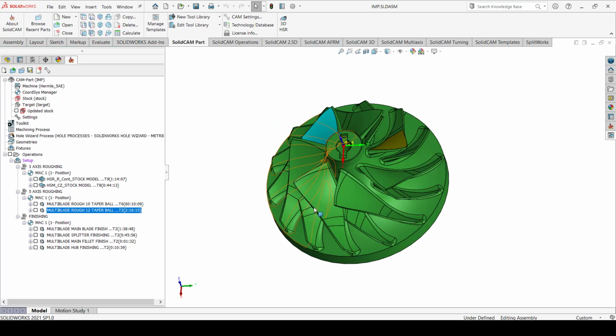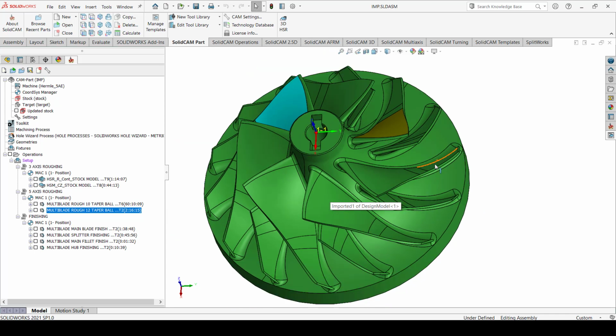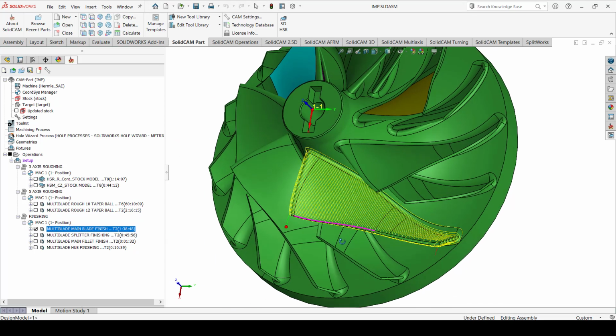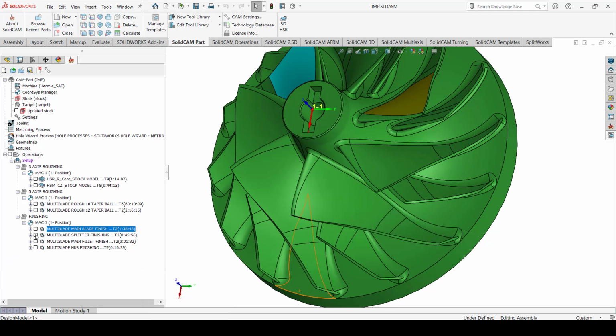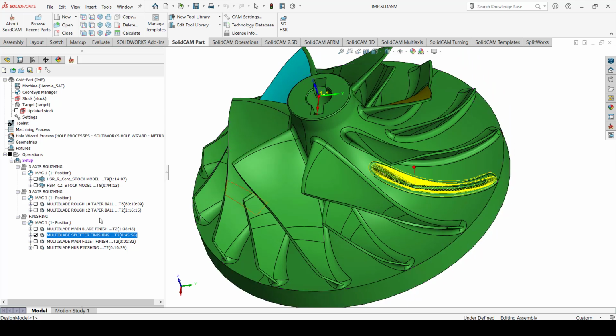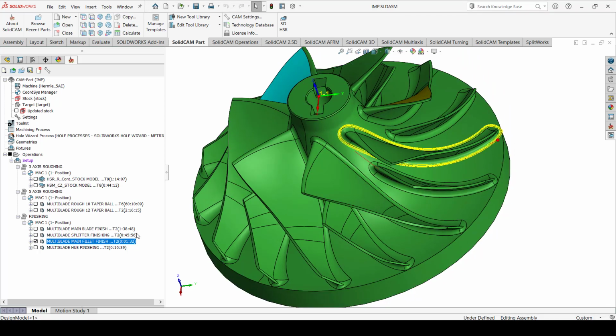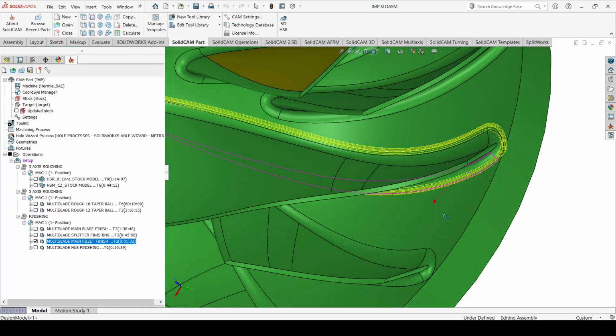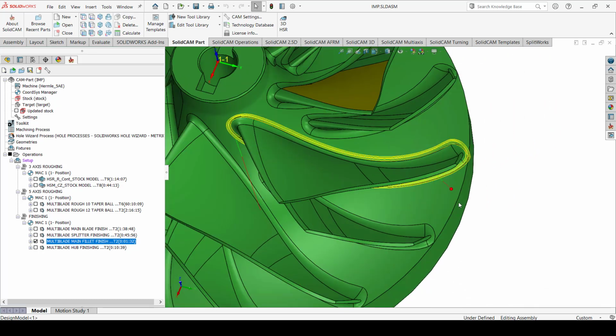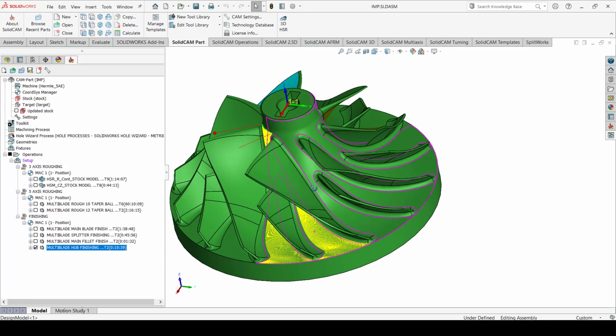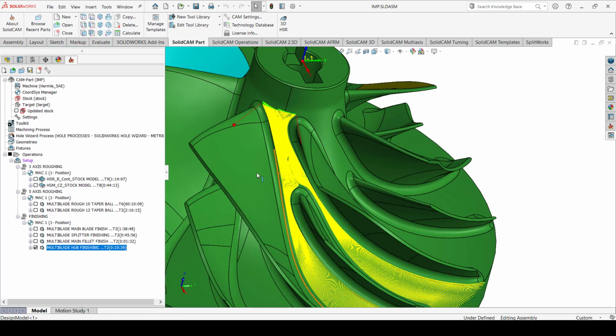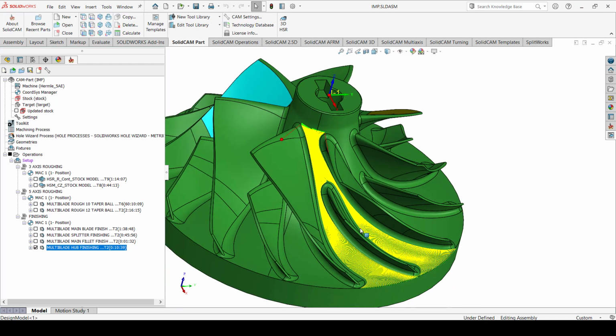Multiblade machining also includes toolpaths for finishing. So you can use only the blade area and generate the toolpath for finishing. You can also generate the toolpath for splitter finishing. You could also generate the toolpath for the bottom fillet only. So you can pick up the fillets and finish the fillets for this blade. And it also has options to do machining for the floor.